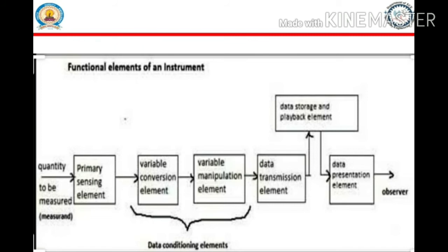Suppose after filtering and amplification, a 1 volt electrical signal is available, it can be identified as 1 kg. If you get a 2 volt electrical signal after the intermediate stage, you can identify it as 2 kg. In this way, whatever variable you get from the input stage will be pre-processed before you derive the conclusions.